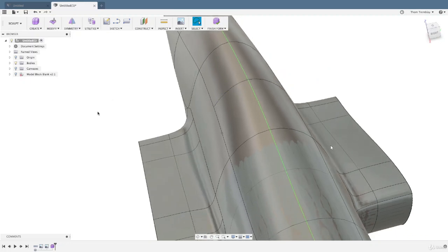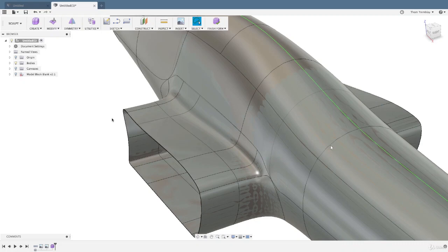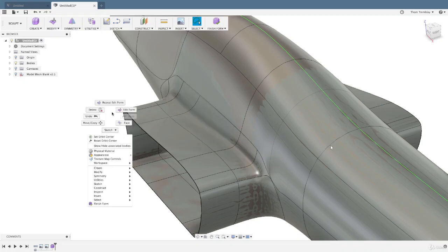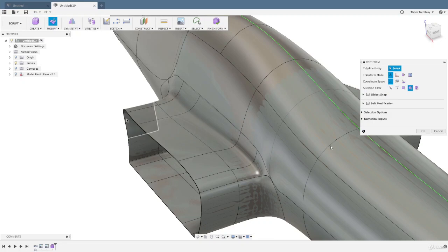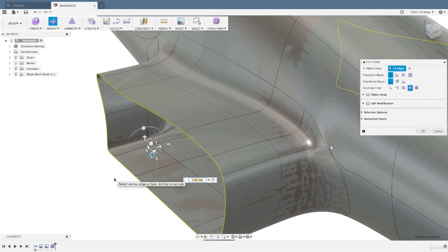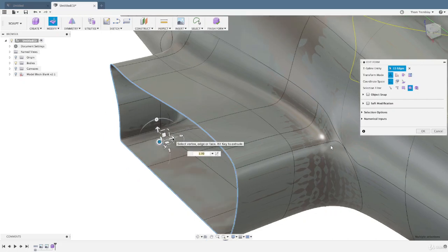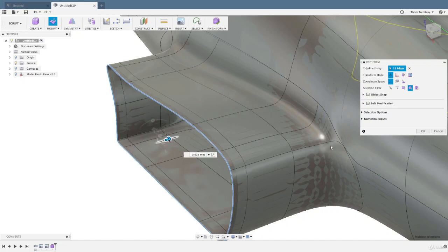And now let's take a closer look at the side pods. The goal is to have the ends of them to be fairly flat. Double-clicking on an edge will select the entire loop, but because the curvature is based on the proximity of edges, we want to add another set of faces. To do this, hold the Alt key and just start to move the cursor along the axis. It will appear as though you're still editing the same edge, but in reality you've created a new set of faces and Fusion 360 has automatically selected the new edges.